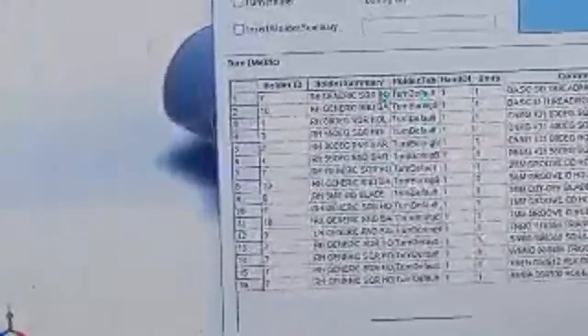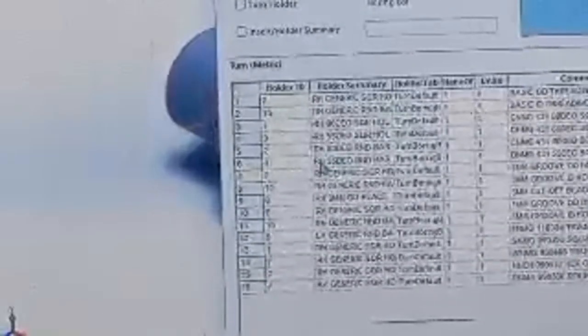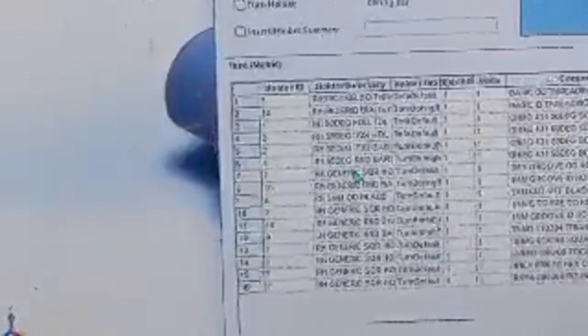You can select the tool you want, the turn tools, all of them will come here. Then you pick the specific tool you need to use so that you use the right tool for turning. All of these tools are here. Because my machine uses right-hand tools, I'm going to use all of the right-hand tools. So they are here. You have to add them. That's how you do it.